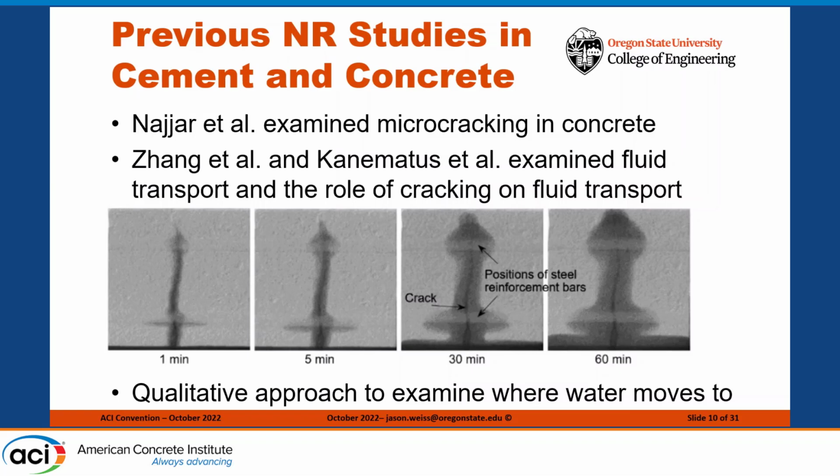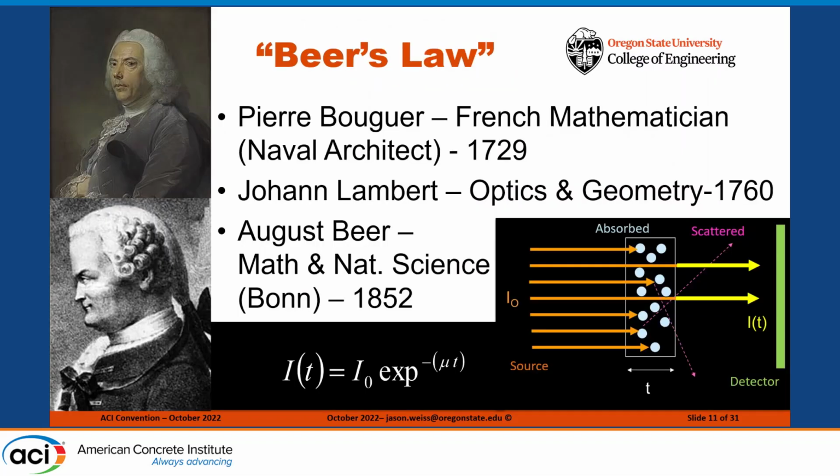You see the crack, but you also can see water that's coming into the system, and what you'll notice is water kind of moving along the level of the reinforcement. Right? This is a very qualitative type of approach, but you can see the water as a function of time moving up into the sample, moving into the crack, and then moving along the reinforcing steel.